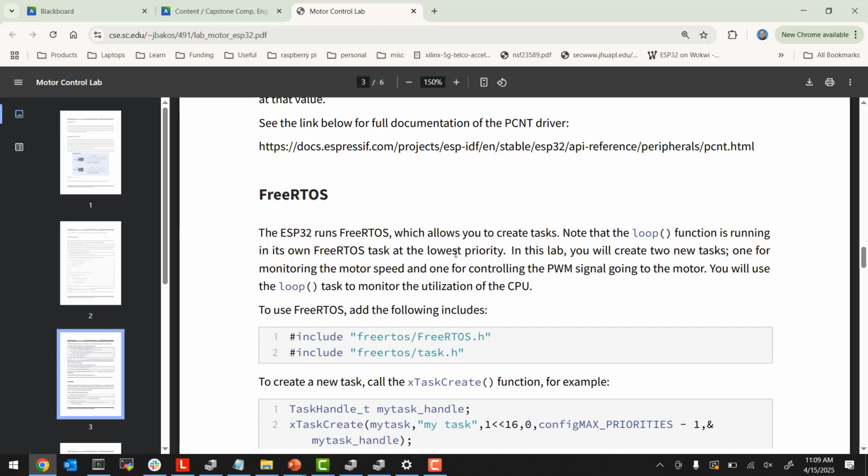It's free, but here's the catch. The catch is what makes a real-time operating system really a real-time operating system is the schedulability check that I just got done lecturing about. That thing I talked about where it determines whether a schedule is feasible, that's what makes it $40,000 a seat. FreeRTOS does not do a schedulability test. It'll let you schedule things that can't be scheduled because it's dumb like that, right? But at least it allows you to create real-time tasks that are schedulable, that are scheduled and preemptible, right?